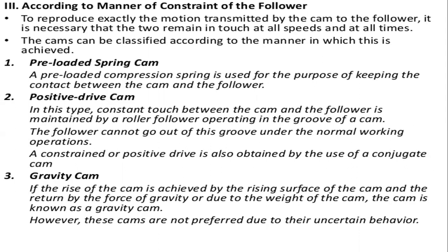And the last type is the gravity cam. If the rise of the follower is achieved by the rising surface of the cam and the return by the force of gravity or due to the weight of the follower, the cam is known as a gravity cam.